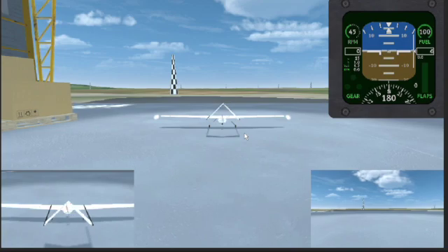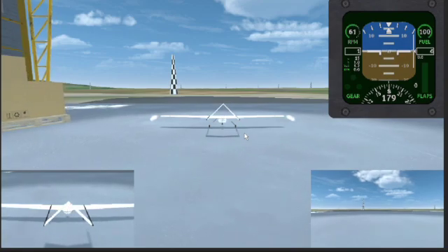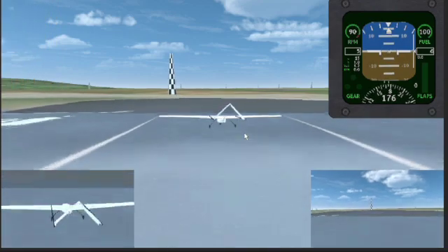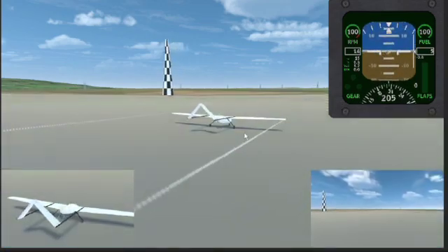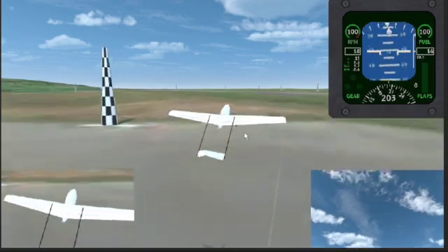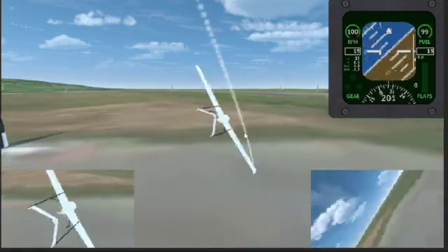The following video shows the UAV taking off with a center of gravity position at 0.1. The right wing stalls as soon as the UAV becomes airborne, leading to a crash, hence why this configuration is not acceptable.